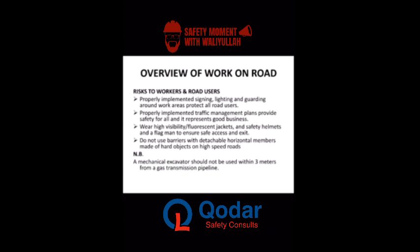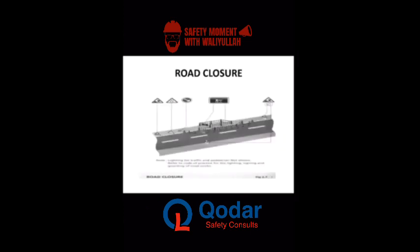Sometimes in some places, when construction is ongoing, there are existing pipelines, gas stations, or gas pipelines that run underneath. Please, a mechanical excavator should not be used within 3 meters of a gas plant or a fuel petrol line below, to avoid causing harm to each and every one of the workers present on that site.